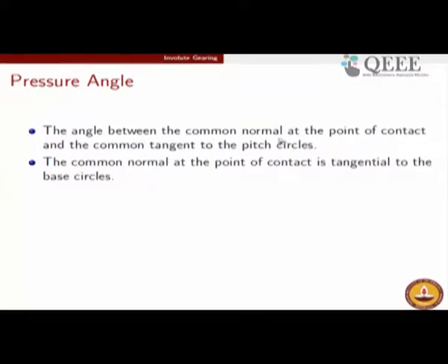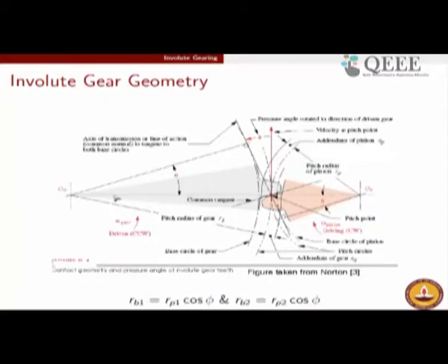The other component is going to simply go to the shaft, and it will cause a shaft deflection. So, the other component is F sin phi. F cos phi is responsible for the torque, but F sin phi, the component which goes horizontally, is going to get transmitted to the shaft itself and is going to cause a shaft deflection. So, obviously, as we said in our discussion of the friction disk also, you would like to keep this component at the minimum.